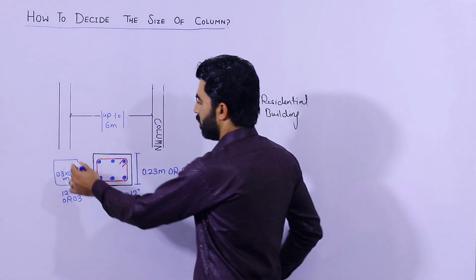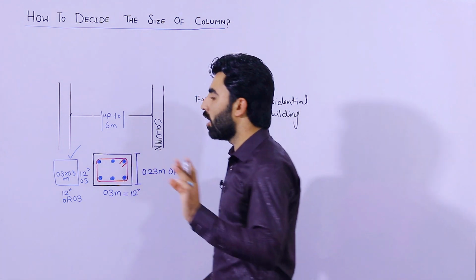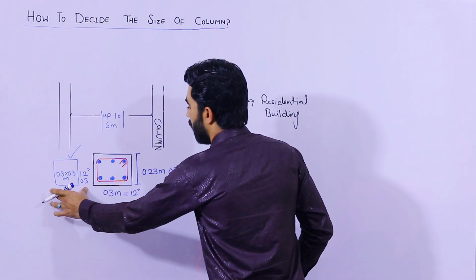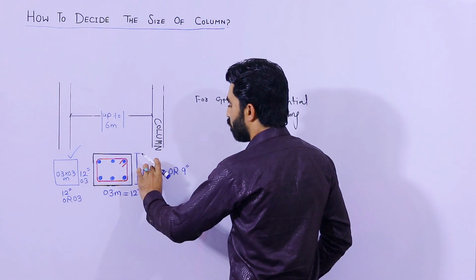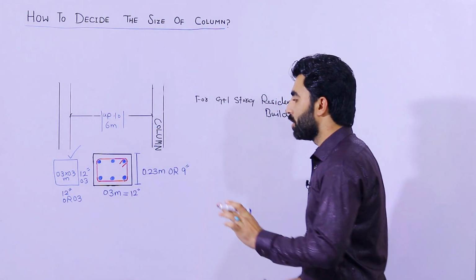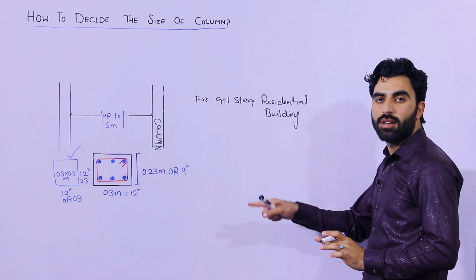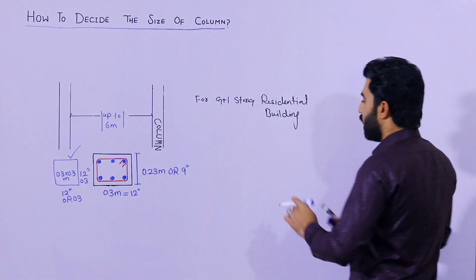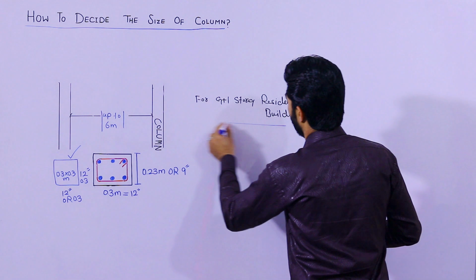So this is best, with factor of safety. So I am recommending this, but it should not be less than 0.23 by 0.3 meter, or 9 by 12 inches.